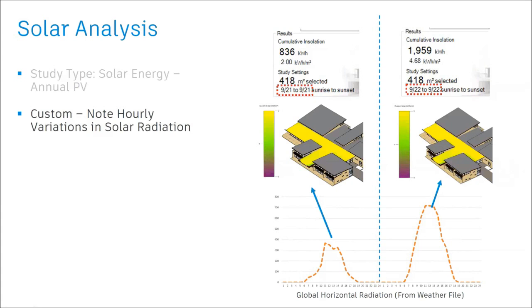So, for example, on your location, it's common to look at days like the 21st of June or 21st of March. They're not always the sunniest days, so it's just worth bearing that in mind. And it's always worth looking at longer periods and cumulative insolation and things like that. So that's just one of the common things that is worth being aware of and how solar radiation works.